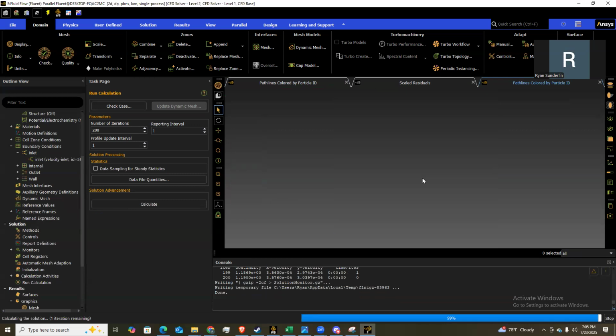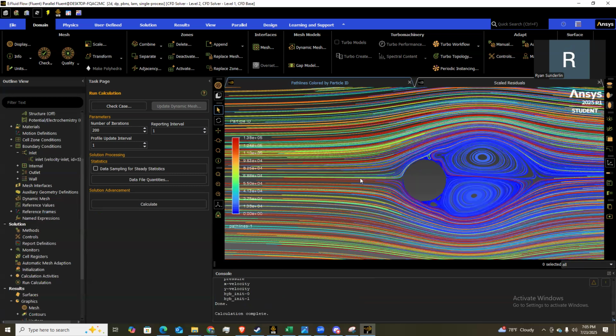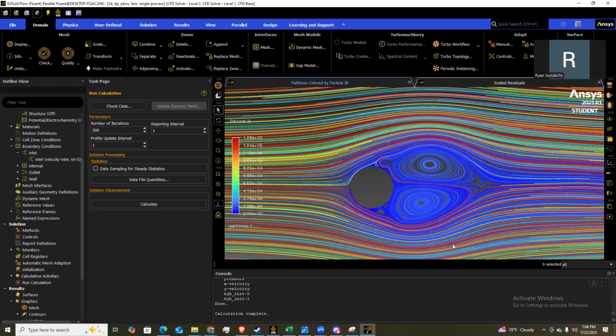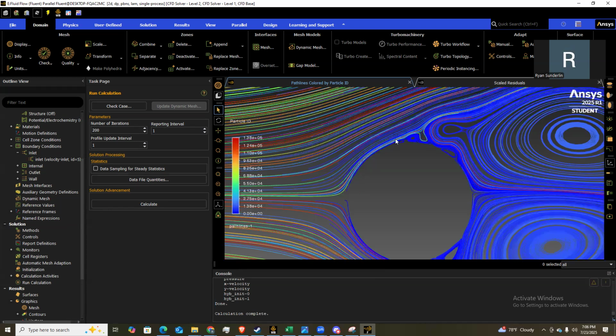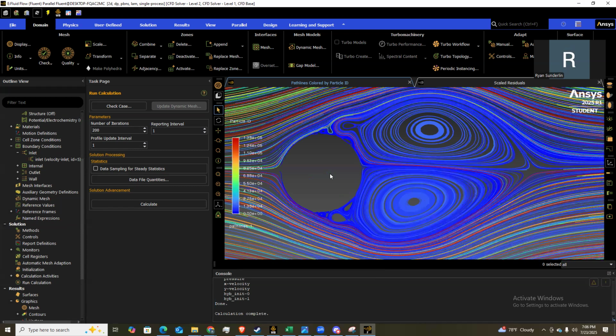All right, and there we are. Now we can see our results for the laminar case. And here this makes sense. There is a huge wake region, due to the nature of the low Reynolds number, the flow is not being energized. So when it hits the boundary layer, it slows down, and then around here, it detaches entirely pretty soon, which creates a huge wake right here.